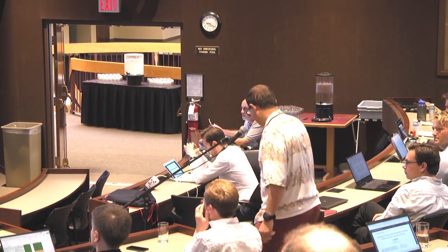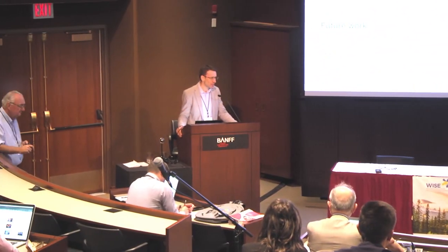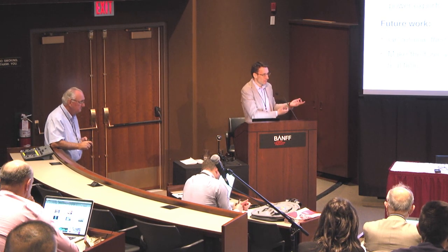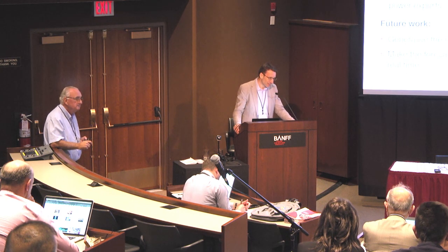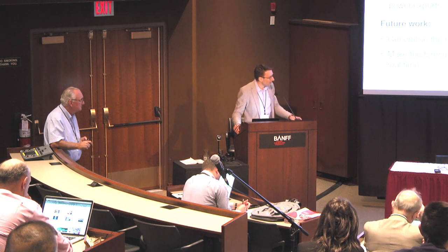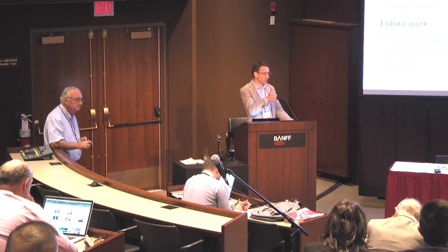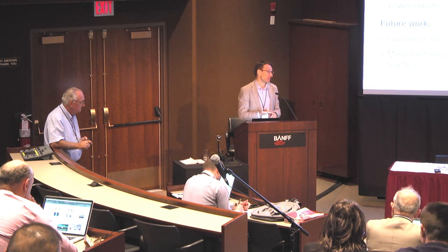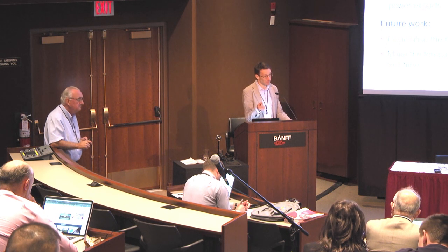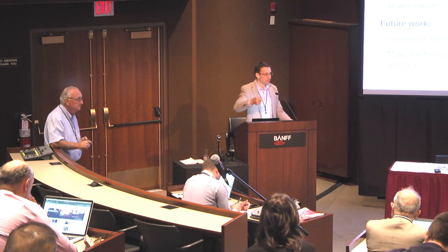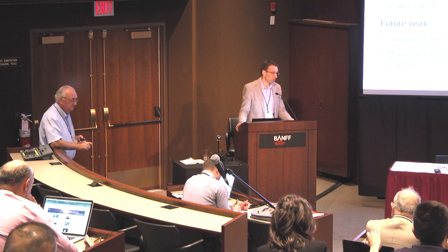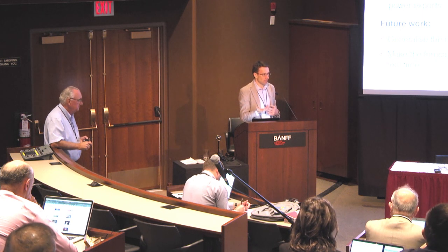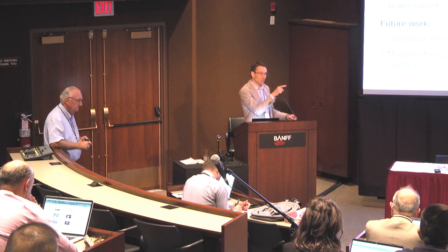Yeah, that's an excellent question, and there's actually a name for that. It's called a death spiral. Essentially, when people adopt rooftop solar, the utility has to charge more to recover the same revenue from the customers who are without solar. That's a well-known problem. So one solution is, first of all, reduce feed-in tariffs. The second solution is where network companies came up with an idea of charging customers for exporting power to the grid. So they still get a feed-in tariff from the retailer, but the network company will charge them to export power. Essentially, implicitly they create an incentive to increase PV self-consumption. But that doesn't quite answer your question.